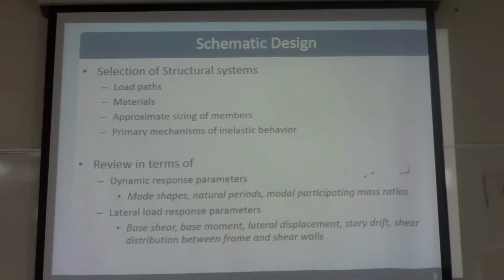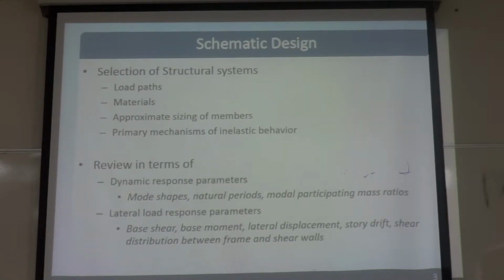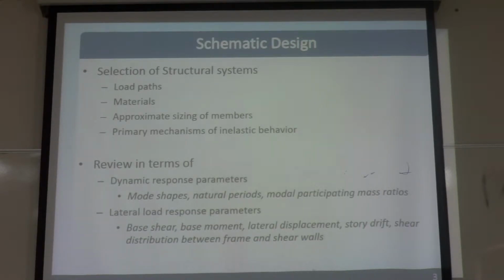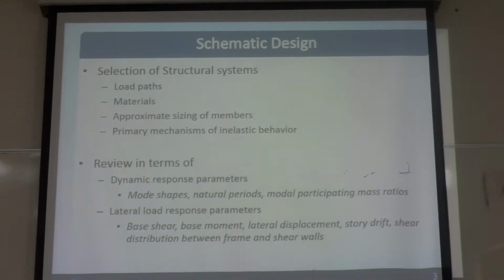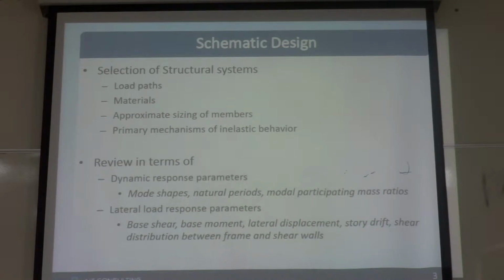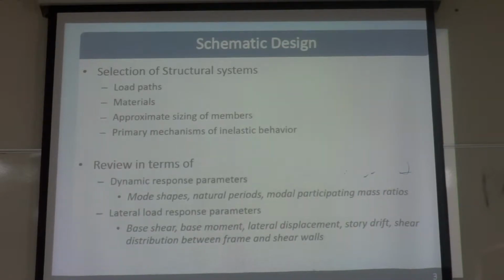So if we use high strength concrete, the member sizes will be smaller. But horizontal members, we use the lower ones. Horizontal members will maybe 5000, 6000 psi, but for the vertical members, for tall buildings, we use about 8000, 9000, sometimes 10,000 psi.